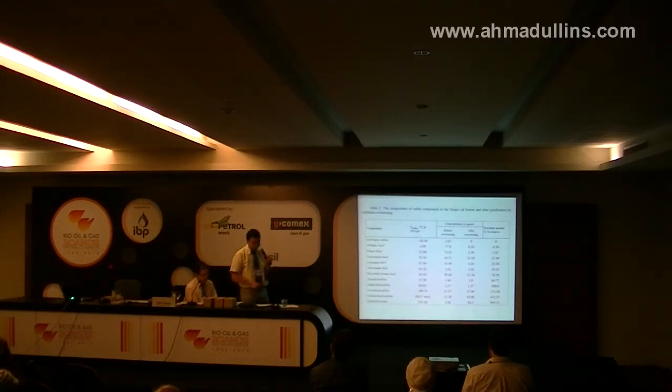See table 2. So from table 2, we can see that the use of oil oxidation sweetening completely oxidized only methyl and ethyl mercaptan. The heavier propyl mercaptan is oxidized only by 70%, and butyl mercaptan oxidized only by 20%.